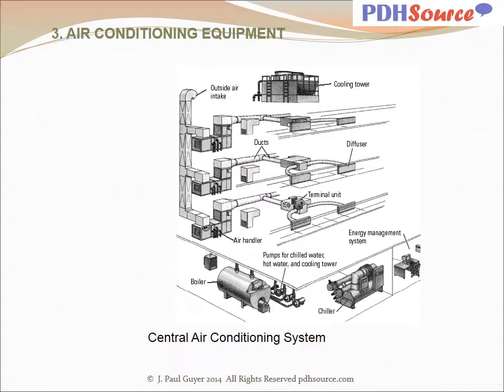It is drawn by the fan pressure up into the plenum space, and then you see a little piece of inverted L-shaped ductwork that is sucking the air out of the plenum and into the fan room.